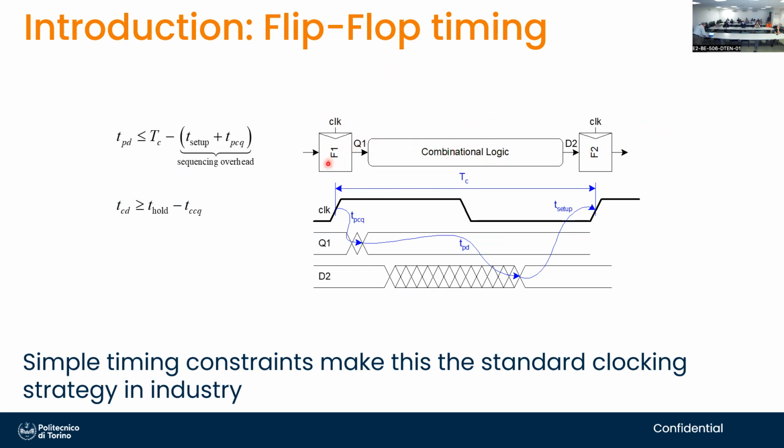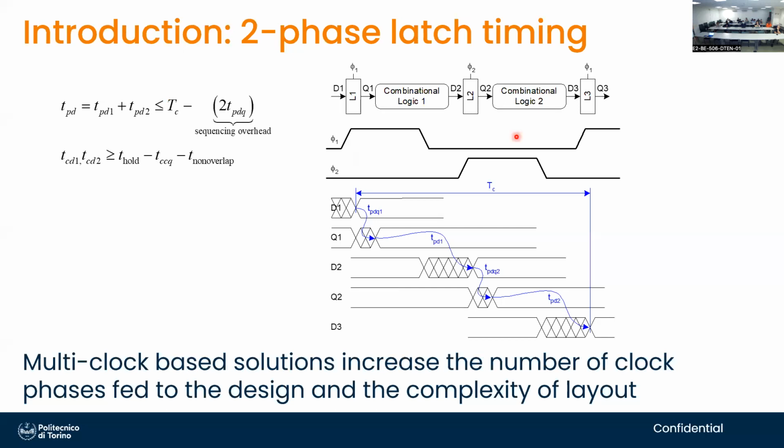And this means that in order to keep everything running, as I said, synchronously, the time the person spends inside this logic here doing work has to be shorter than the clock period, because at the next clock edge, the person will be allowed and actually required to exit. And at the same time, we cannot have a person going through two doors in one clock cycle, because that would be a violation of the protocol. You'd be doing too much work in one clock period, and that would make the system not work as expected.